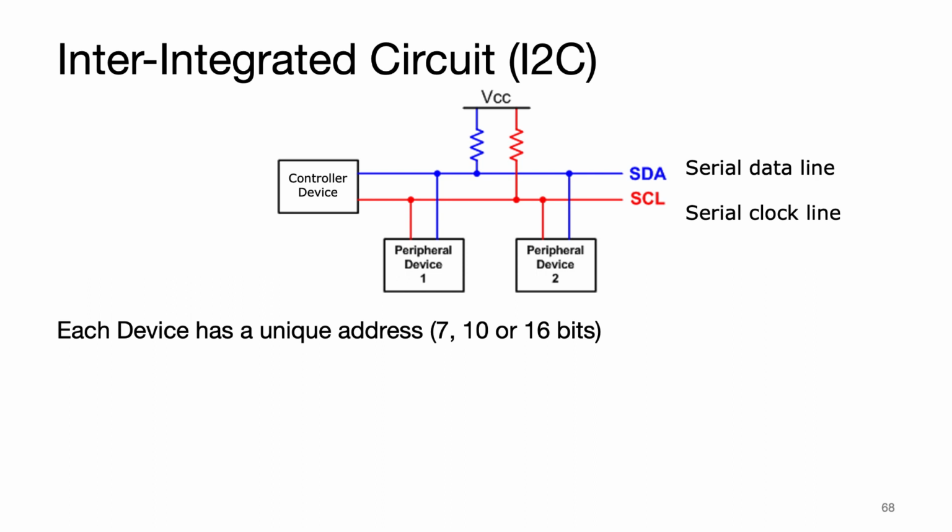And if the device manufacturer says that they're all the same address, you can't put multiple peripheral devices on the same bus because they'll all try to respond. So you say, what's the range value? And then multiple devices try to respond at once, giving you corrupt data. There's ways around it. There's bridges. There's other hardware you can use to get around that.